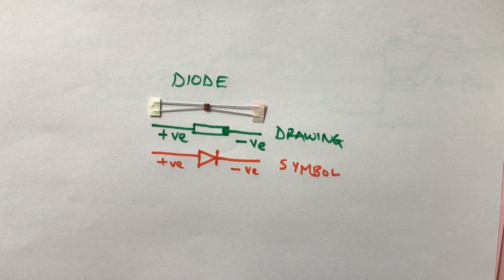Trust me, if you start rotating it round and round, it will change from being a motor to becoming a generator, and it will give out small amounts of current, which will result in power. We always avoid that by using diodes, so that we create a small loop where that small power generated will cycle in, instead of getting back to our main circuit and destroying it.